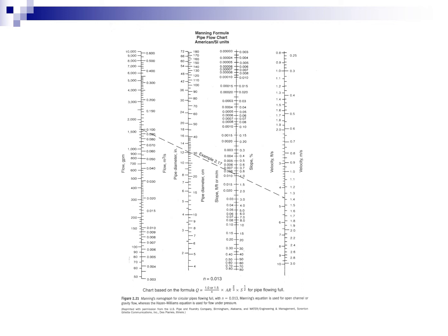So if you are between common sizes, the best practice is to size up and go up to the next larger size. So if my line said, oh, I need an 11-inch pipe, there are no 11-inch pipes available, but there is 12. So I would then put a 12-inch pipe in, because that is something that I can get.